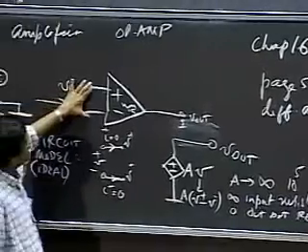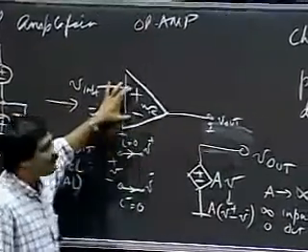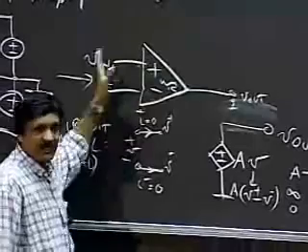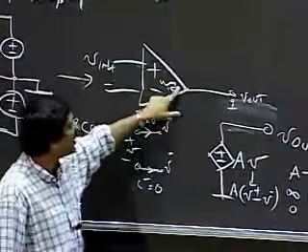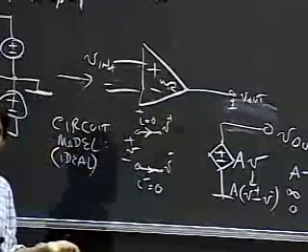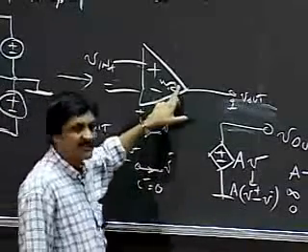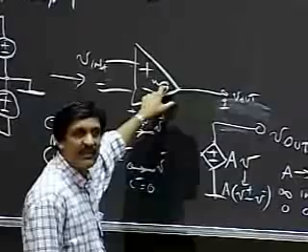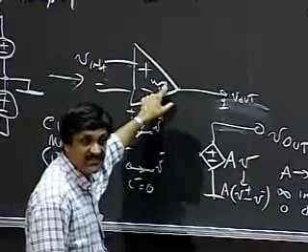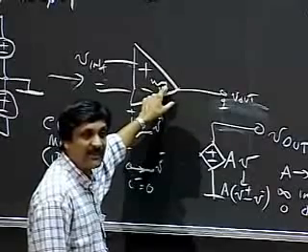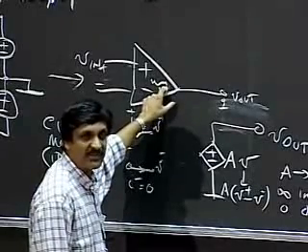So that input stage is what's inside the op-amp. It's got a bunch of other circuitry like level shifters and so on, and at the output, it's got a buffer. At the output, it has something reminiscent of the source follower circuit that you learned about in recitations, a solved example in the course notes, and in your homework as well.